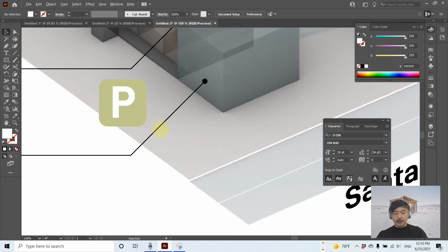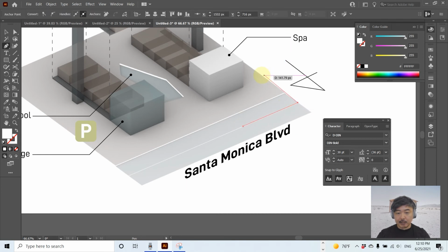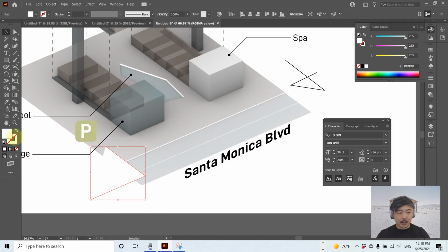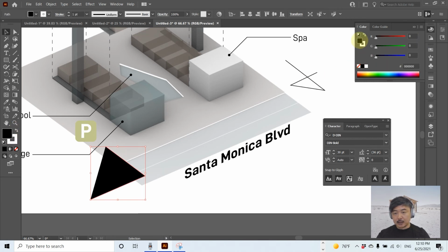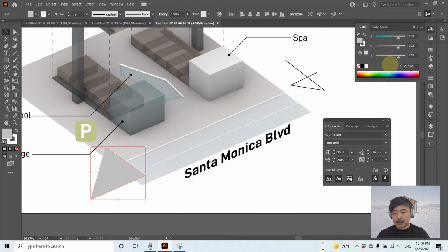So how the vehicles will enter the site, you can just draw it like, in America, it's right side driving. So you can draw a line, borrowing the geometry, and then you can come in from this side and then change the color to be, oh, I don't know, relatively light white, and then no fill.